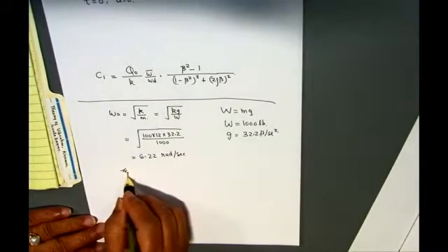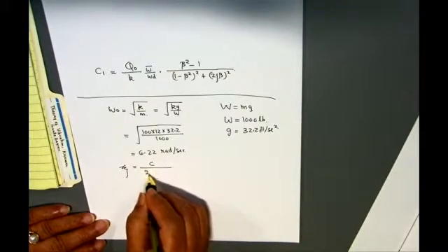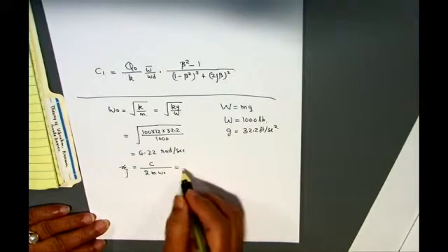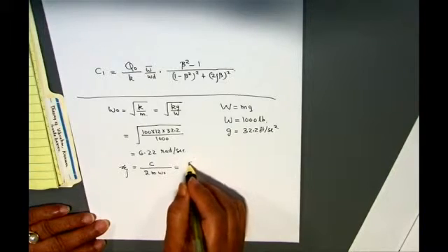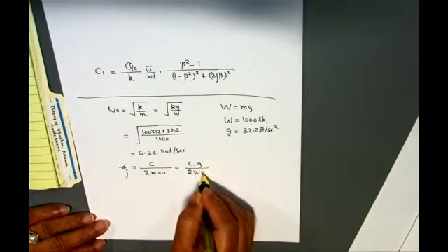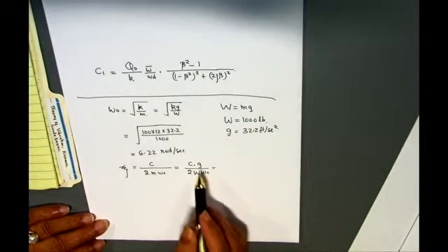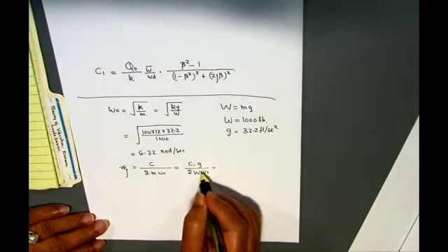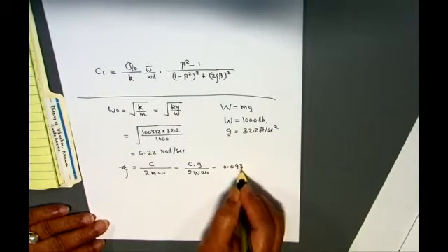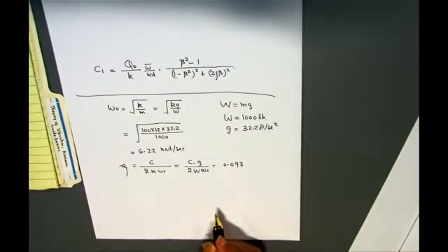We also can calculate zeta, which is the damping coefficient c divided by 2 m omega 0. Again, m is mass, so we need to convert into weight. So we can do c times g over 2 w omega 0. We can input the value of the damping coefficient. We know the weight, we know g, we know omega 0. So we will get this value as 0.093, and this value is much smaller than 1. So this is an underdamped system.